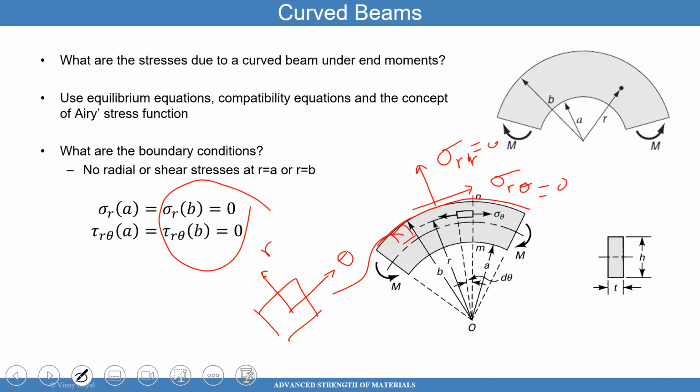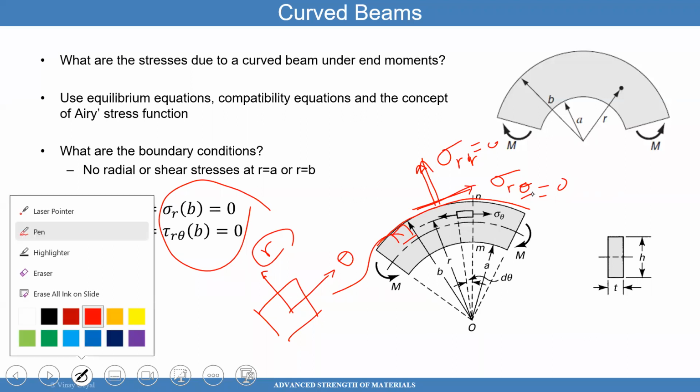So you can see here that normal to the surface is sigma RR and tangential to the surface is sigma R theta, because in sigma R theta the first index corresponds to the surface we're talking about, which is R, and theta here is the direction that we're applying the load. Okay, so hopefully that's clear to you.